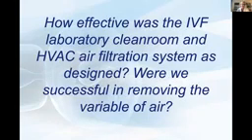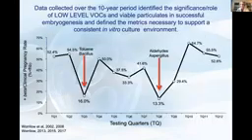So how effective was the space? Were we successful in removing this one singular variable? The answer, after 10 years of studies, yes, but not consistently. And it's really the drops in some of our clinical outcomes, and then later the association of these drops with a breach of integrity of our HVAC system, the entry of parts per billion VOCs, and very low-level viable particulates or bacteria, viruses, and fungi that actually countered the success that we had been having.